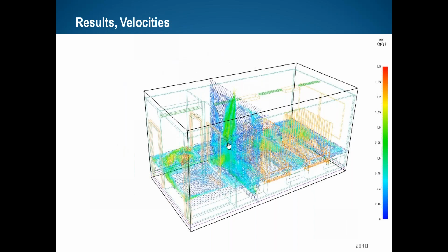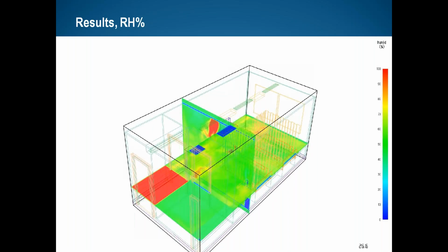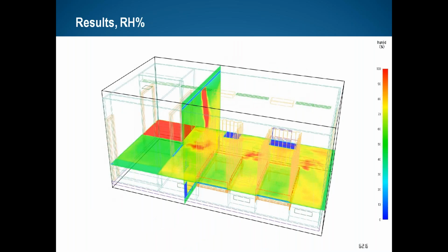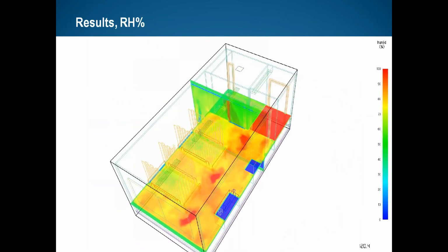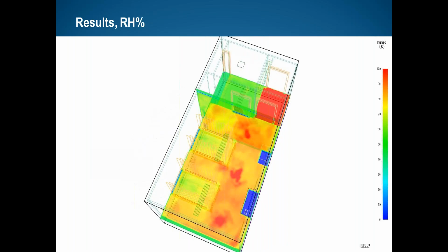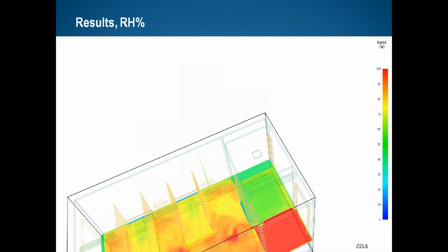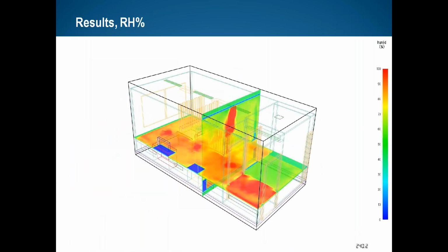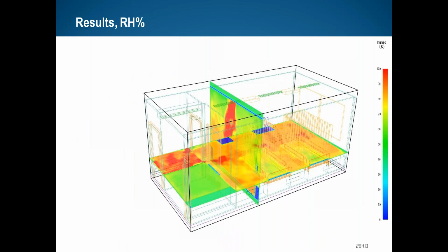Here the relative humidity, the same. By the way, these case studies that we are describing now, we have 40 cases for the air distributions and for the number of air exchange, because we need to make the design able to scavenge or dry any residuals of the sneeze or cough, okay, so it can be moved with the air to the floor and go out, and then in the void of the rest floor we can sterilize it or whatever.